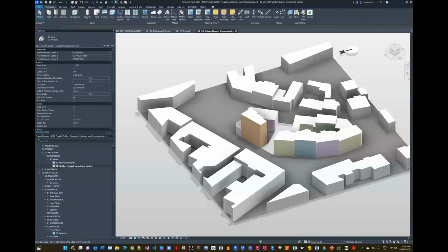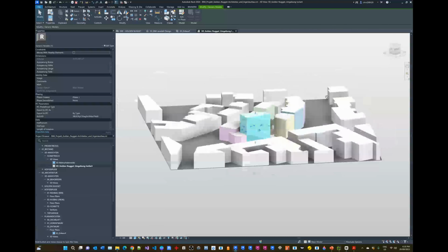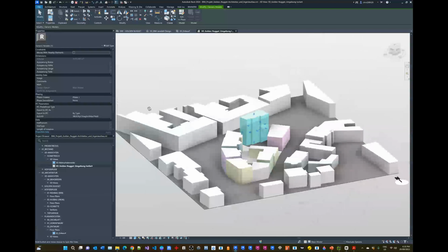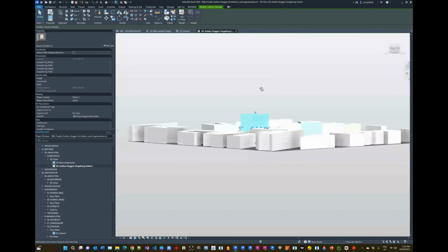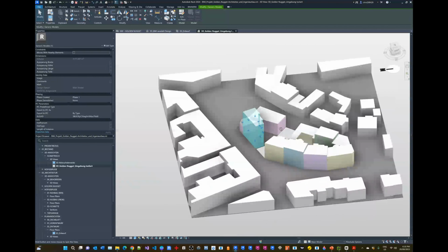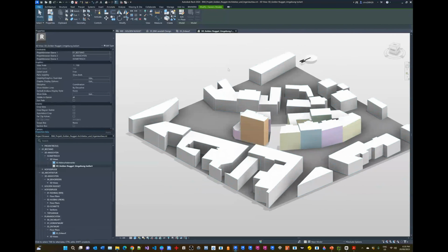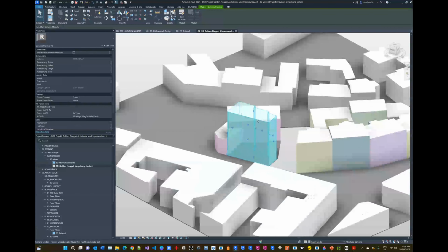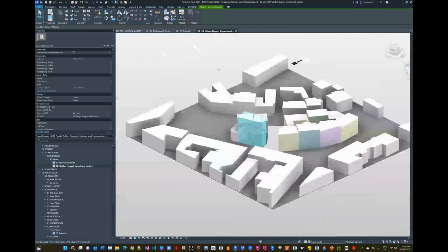Notice I do that by moving my cursor over the element and left clicking. Then when I do the rotate function, that will become the center point or focal point of my rotation in the model. So now that it's selected, my rotate is occurring around the object that has been selected. Okay, so that makes it a little bit handy when you need to focus on something and orbit around something. Make that the center of your Revit universe, so to speak.